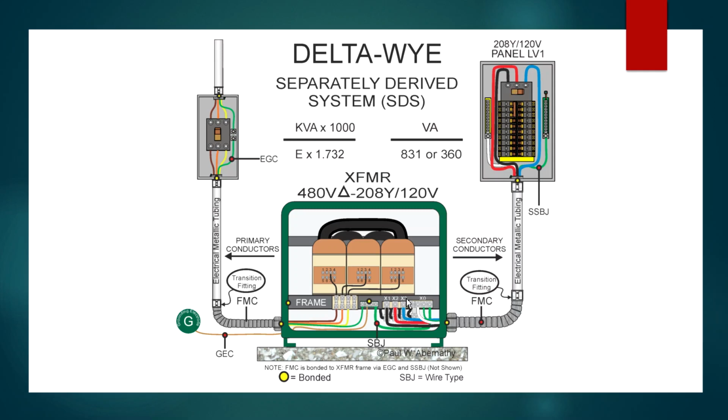Now it could actually be right here at the secondary source point where the voltage is derived from the secondary. But typically it's not. If it was right here, then you size everything downstream based on whatever the load is. But in this case, since we have no overcurrent protection here at the actual source of these secondary conductors, where they're derived, then we're using maybe a 10-foot rule or even a 25-foot rule to size these conductors, okay? And then the overcurrent protection is right here.